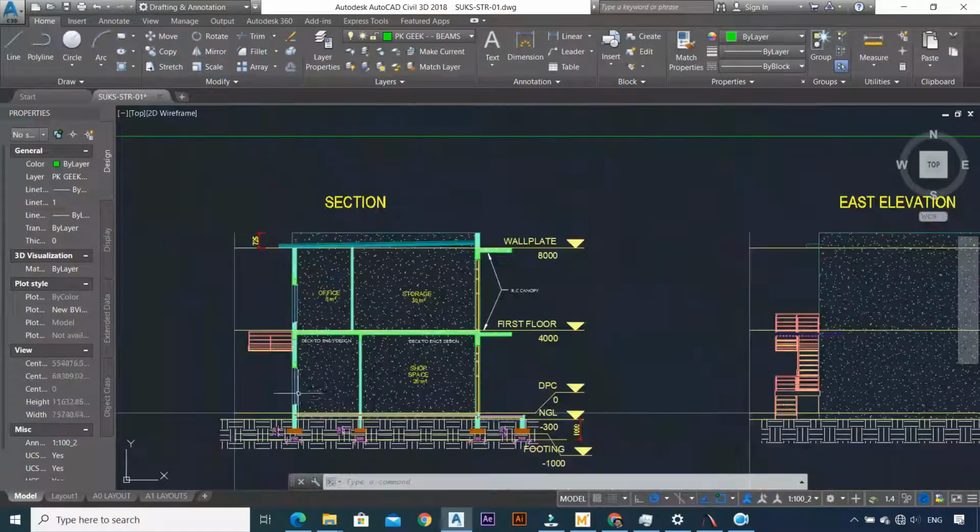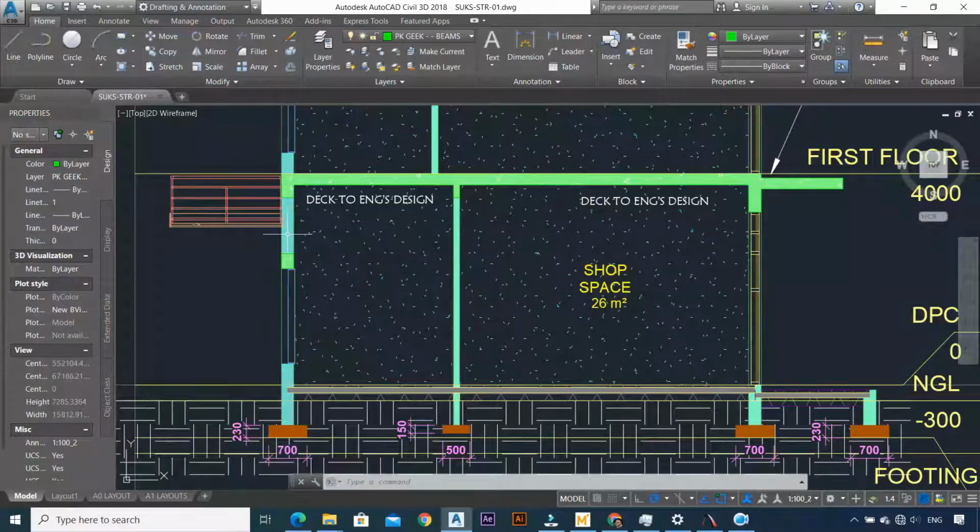And then that load is then going to be carried down, including the self weight of all these columns, down to the foundation. That is what we're going to use as the actual loading that is going down to the foundation. And remember, we don't have a ground slab or ground beams, so what it just means is we don't have any load coming there. This ground slab is going to be bearing on the soil. This is where my mouse is, so that one is not going to be transmitting its loads to the bases for this.